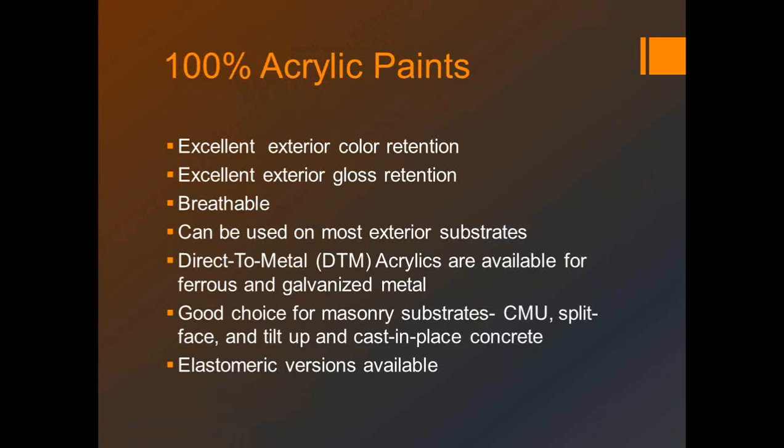I got a phone call from a painting contractor here in Nashville yesterday. We've had about 3 or 4 days of steady rain. It dried up a little bit yesterday, but he called me up and was complaining because he had blisters all over the outside of a house that he was doing, and it was an acrylic paint system he was using on the outside of the house. For anybody who's ever run into that, that breathability factor is part of that, because vapor barrier can build up behind these fresh films, and you can get moisture collecting behind.